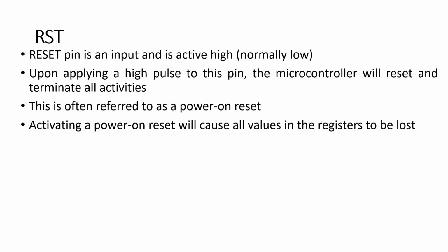Let us talk about the reset pin of the 8051. Reset pin is an input and is active high. Whenever you apply a high pulse on this reset, the microcontroller will automatically reset and it will end all those activities which are in execution. This is often considered as power on reset.